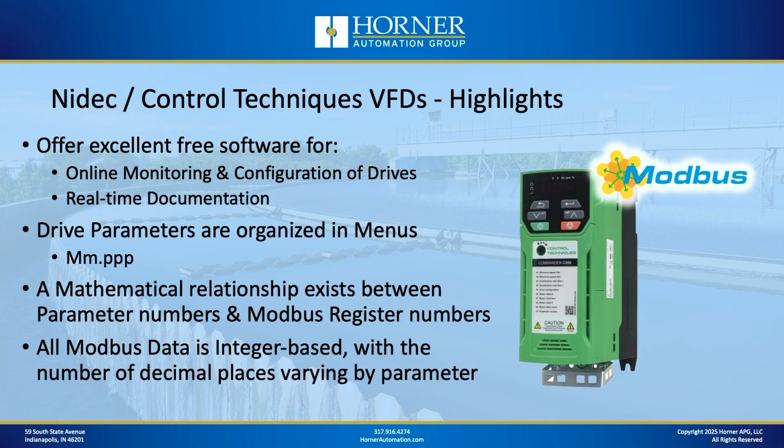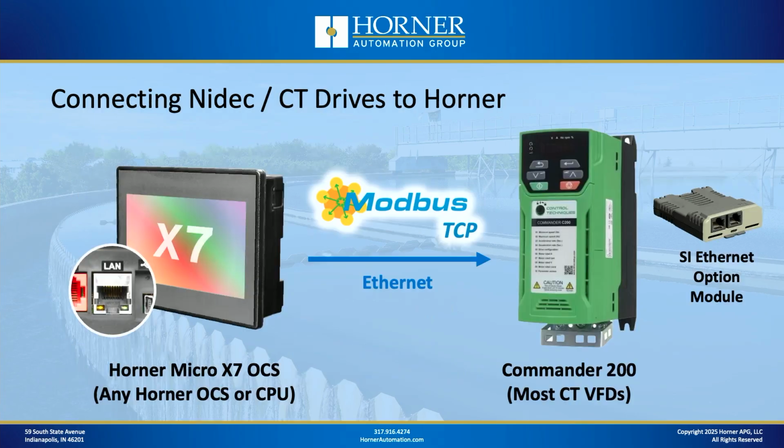It's really very nice. Now, all the data available over Modbus is in integer format. So what you won't find is any 32-bit floating point encoded values, which means all the values of all the Modbus registers are accessible in integer form. If there are any implied decimal points, in tenths or hundredths, etc., those are documented in the parameter listings.